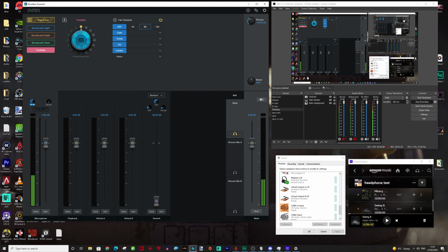The fact that when you've got all this stream stuff coming through, you're also going to want to plug your headphones in, that is a big con for me, that you didn't go high impedance on this. It would have been something that I would really like to see, because unlike Beacn, you don't have the option to output to another output device, although obviously you would get latency there from your microphone. It's just a little bit annoying. But at the moment I'm using Sony MDR7506s, which are like 54 or 64 ohm headphones, and there is plenty of power there. But it would have been nice to see a little bit more power.